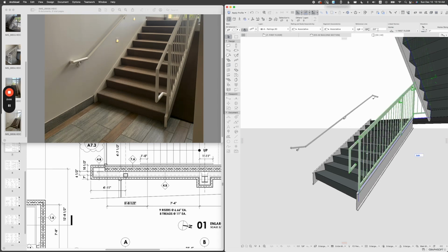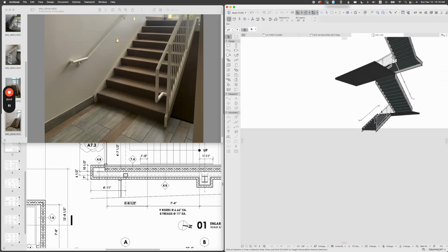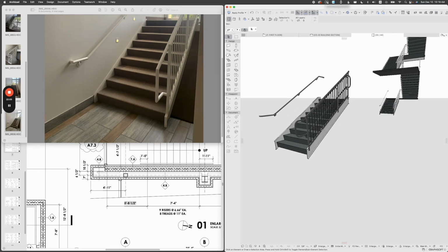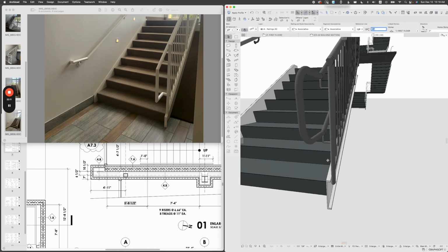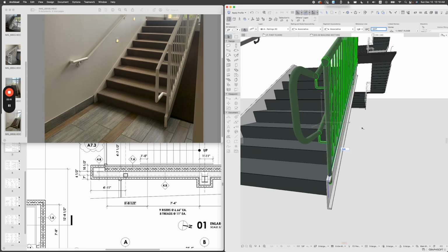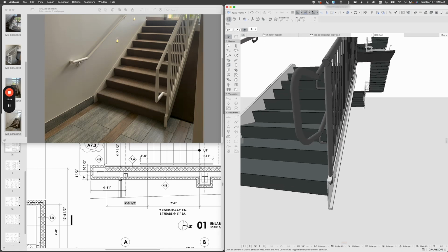And now I will just quickly select this particular guardrail and check what was the reference line offset that I did. Okay, it was -3/4. I'll just copy this number so I don't make a mess again, to speed up the process a little bit, and select it. Just type this number here, because you see it's not really sitting where it's supposed to be. So I'll just paste that particular offset here, and this is exactly working now.